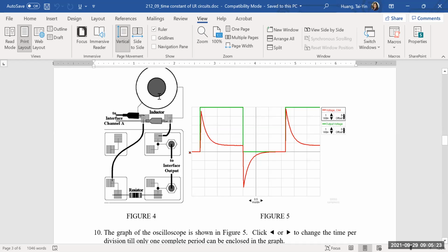Now, when you measure the inductance, make sure that you do not power the circuit. You should use a voltmeter to connect to this spring before you do anything. Measure that, and then you set up the circuit. You should have 1 wire lead connecting this spring to that spring, and another wire lead from this spring to that spring. These 2 connect to the black box, and then you have the resistor right here. So you can see that this forms a series circuit.